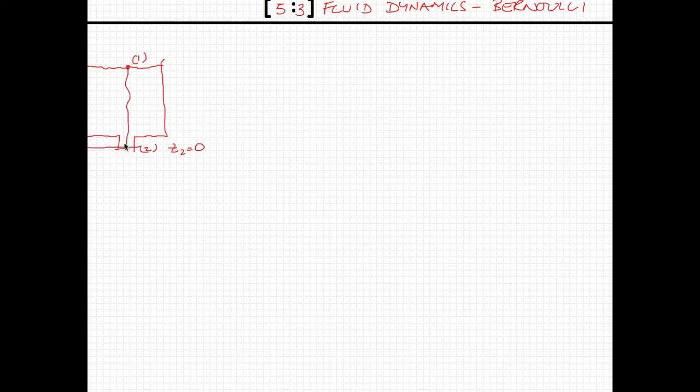And it's not completely esoteric because it also relates to the behavior. For instance, without getting sidetracked here, if you have a well in a porous medium and you initially have a water level in the well, and everything's at steady state. This is the water table maybe, and all of a sudden maybe you drop the level of this well by some amount, so that instead of being here, it is now here, then what would you expect to happen? You'd expect to have flow into this well that would fill it back up to this initial position.